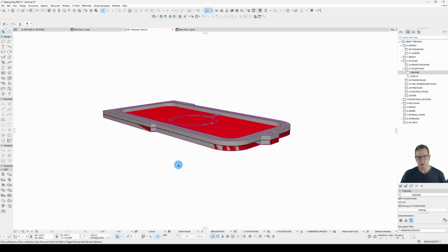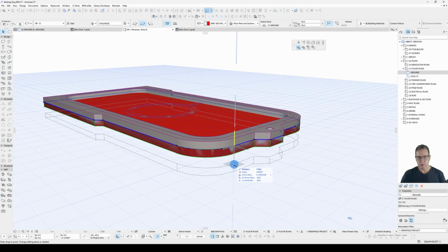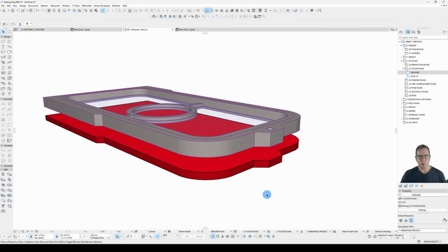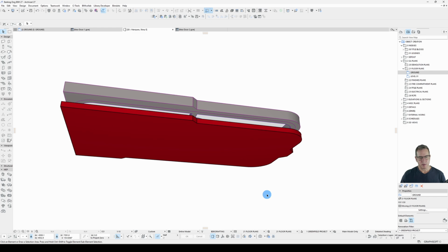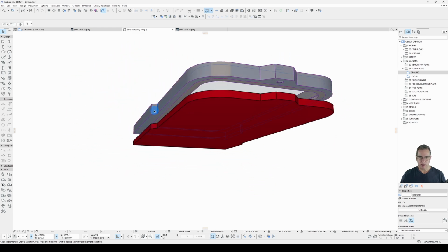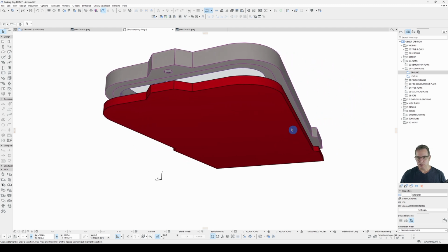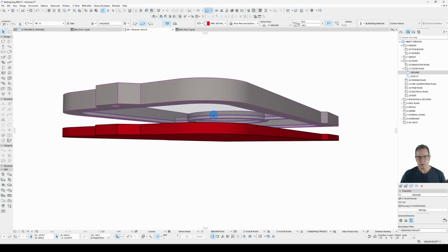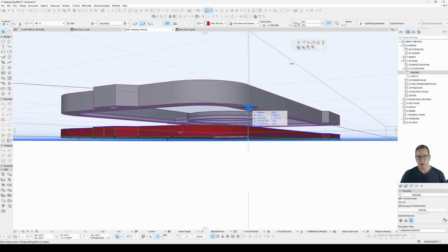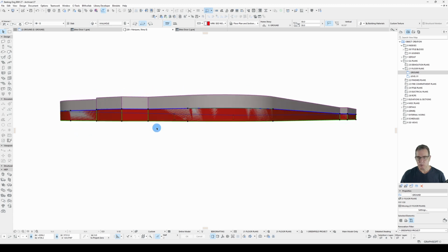If I have a look at that in 3D, what you need to do to create your wall opening is create a slab that represents how you want the wall to be cut. So in this instance, even though strictly speaking it wouldn't be how it would actually be done, but for demonstration purposes, we want to cut our wall opening like this. I've created a slab for the cut. I align the bottom of my slab with my Z0, which will represent the external face of the wall.